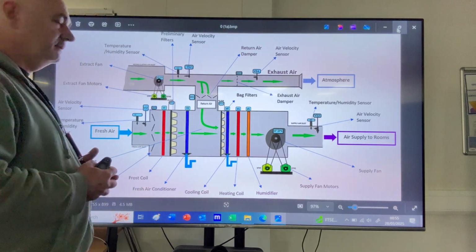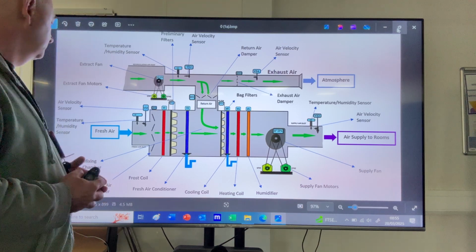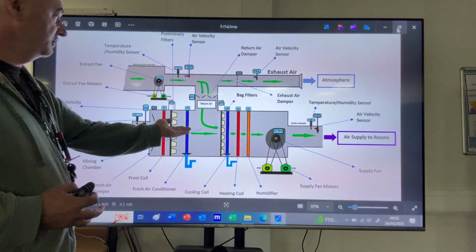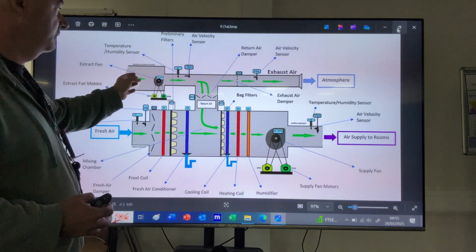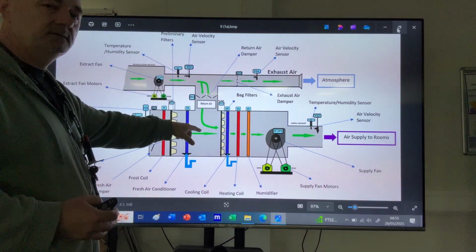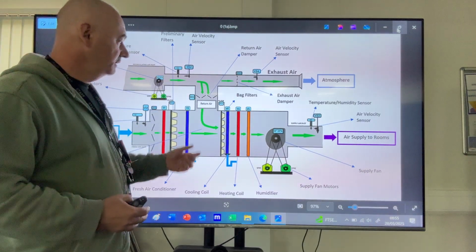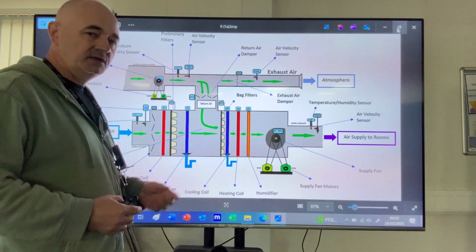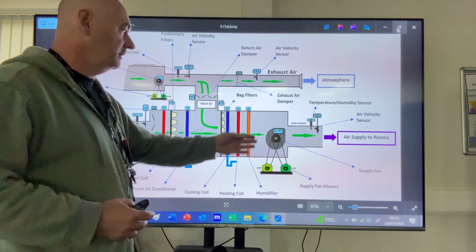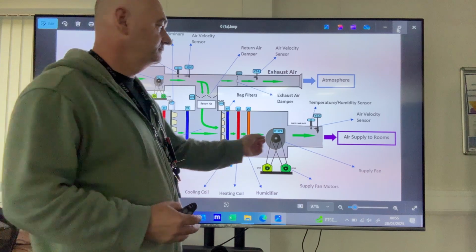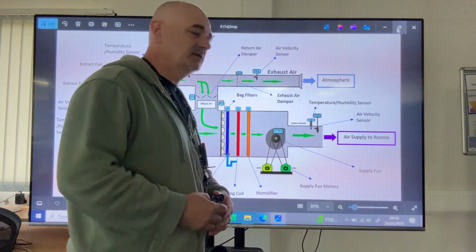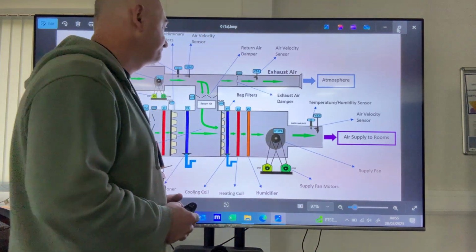You'll also see how the air circulates through this AHU. You can see we bring some fresh air, and we also recirculate a quantity of air. The recirculated air meets with the fresh air intake, and it goes via the supply air chamber. It is pushed into the duct and it goes into the room.